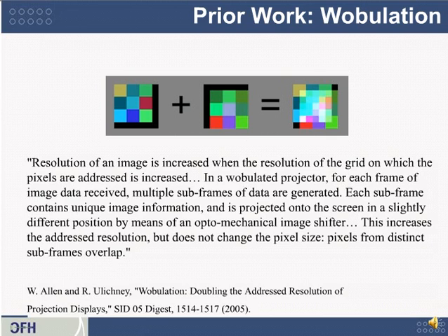So HP had this technology that I believe might have also been used in some TI HD resolution televisions, in which a half HD resolution DMD was made to create imagery that sort of looked like HD resolution by vibrating the image back and forth a subpixel. So the native pixel size is still quite large and blocky, but if you integrate, you can introduce new high-frequency information.